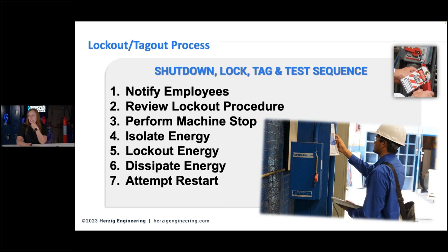Typically, the last step is to attempt to restart. Make sure that if you did try to turn everything back on with the locks in place, it won't. That energy will not come back on. Then you know it's safe to get started to work.